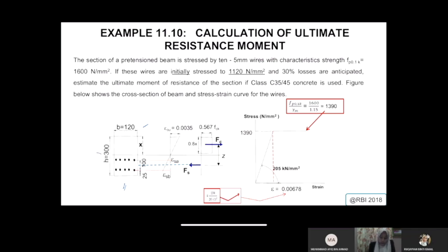What you will see here, we have provided, which means that we have designed the pre-stress beam by providing 10 5 mm tendon. It depends on you how you want to put it in your beam. But in this case, they put it in 2 layers, which is 5 below and 5 upper. By putting 2 layers of tendon, you will have 2 strains contributed from your tendon.